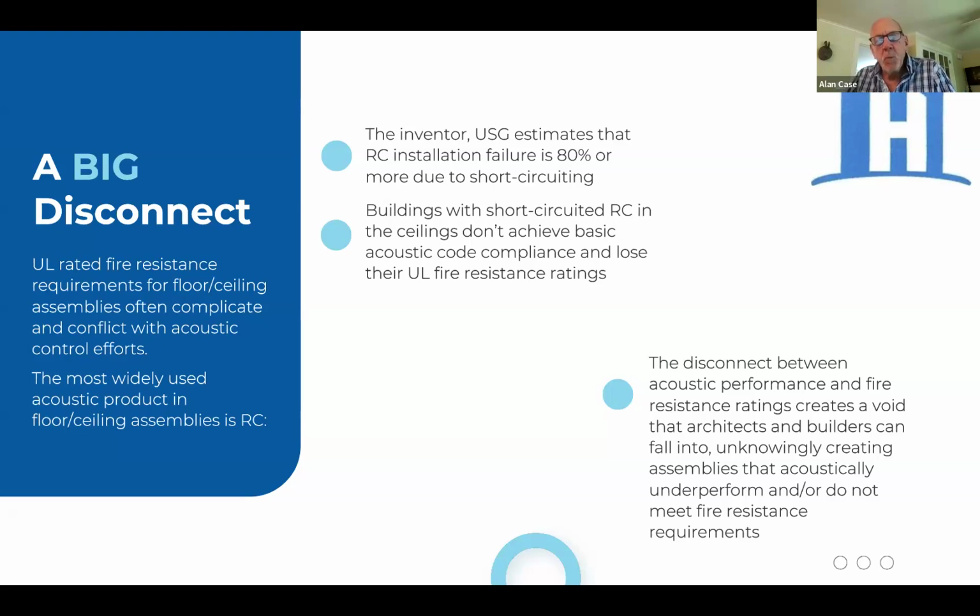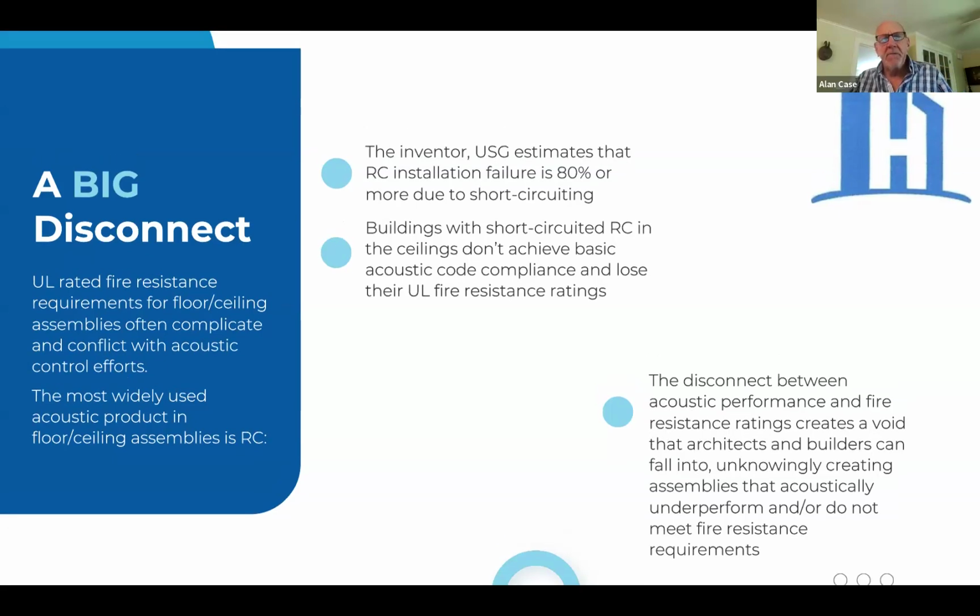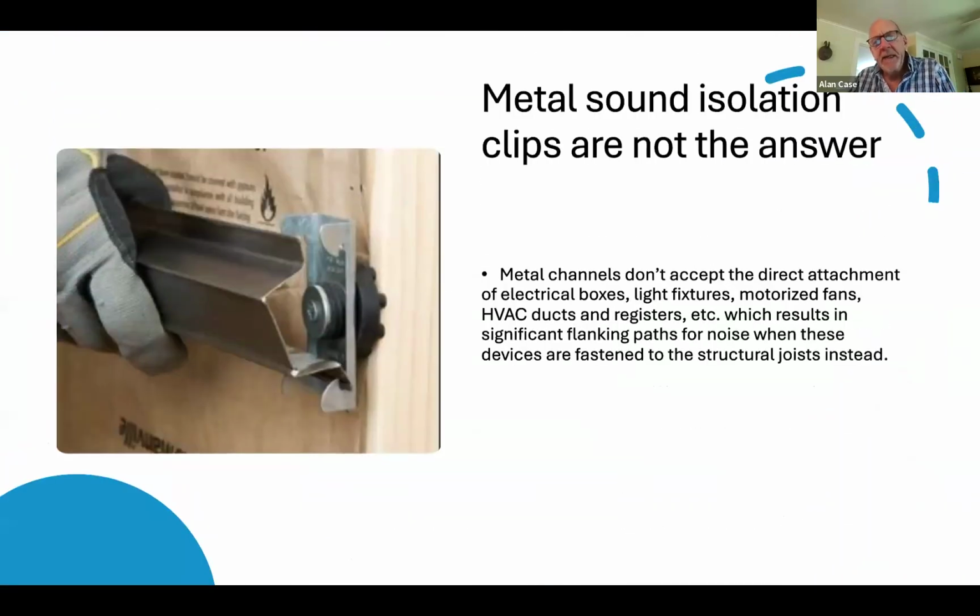But what you'll typically find is they're actually using a big pair of water pump pliers or things like that to just squeeze it down. And when they do that, it crimps the channel, and they don't sit quite as tight as they could, and they vibrate, they bounce around. So it's not a perfect situation, and it really runs into trouble when you get into fire code issues.